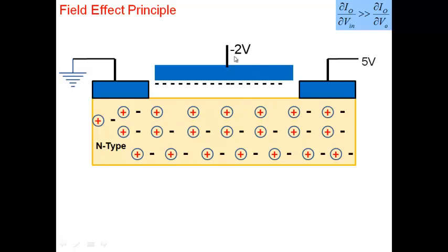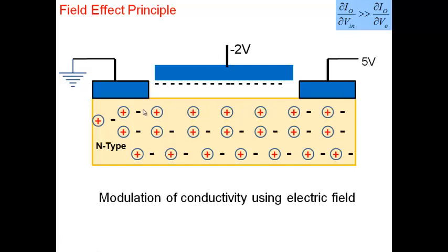And this is like the other plate. So when you apply a voltage to the capacitor, -2 volt, what happens is you acquire negative charge here. And these electrons from here, they go through this terminal and come over here. So the electrons line up here, leaving behind a positive charge here. So you get positive charge on this side, and you get negative charge on this. Okay, so it's basically like a capacitor here. But the consequence that you realize now is that if I apply a negative voltage, it has removed electrons from close to the surface, and therefore I get a change.